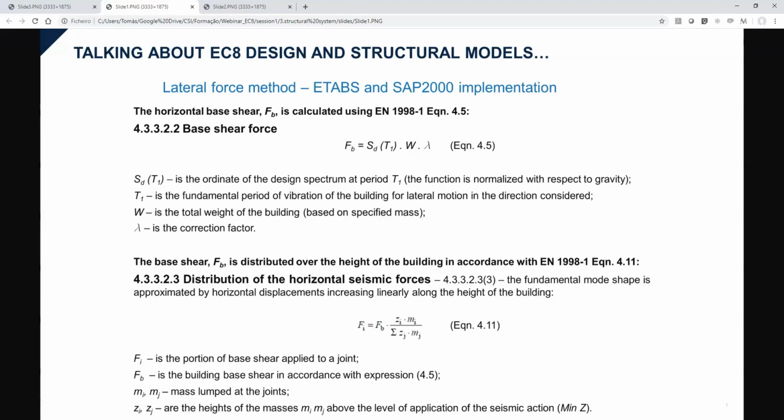Since we are dealing with a relative classification, meaning it depends on the relative forces between walls and frames, the question arises, is the magnitude of the earthquake very important? Generally, no. It is not very important. I would say the most important thing is to follow the seismic definitions, but specifically the vertical distribution of the seismic forces so that it resembles a normal earthquake as much as possible. Therefore, while we will use the seismic definitions I will explain, the maximum reference magnitude applied during this classification stage is not critical. Another very important question is defining which model will be subjected to this earthquake, the primary structure or the global structure. And also, with what type of element stiffness, the 50% reduction.